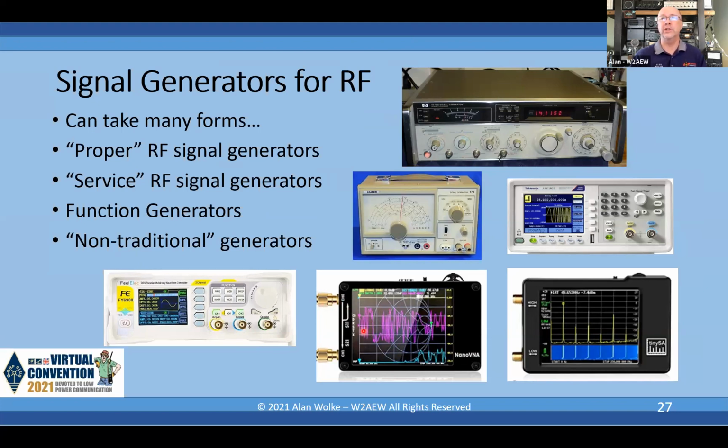Okay, and you can't adjust the amplitude of it. Even the tinySA has one feature where it can be used as a signal generator. I don't know whether that signal generator output is adjustable in amplitude, probably not, or probably not by much, or whether it's sinusoidal or a square wave. But in a pinch, they could be used as signal generators.